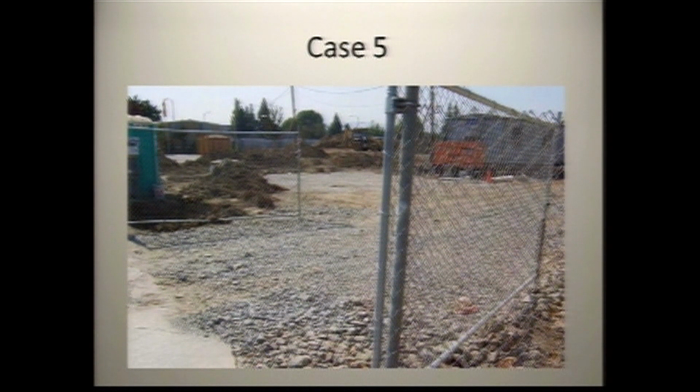If you get a sharp version of this picture, you can see that the voids of the rock are actually filled up with dirt. And the point being here is that these things have to be taken out and new rock put in, new fabric and then new rock down, because after they fill up with dirt, they're not going to really function anymore. They're going to be kind of a net zero, and so those have to be maintained periodically.